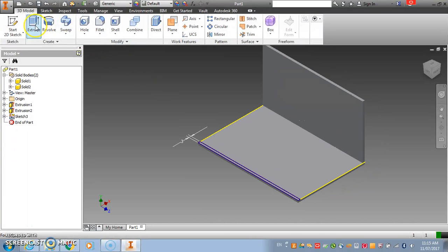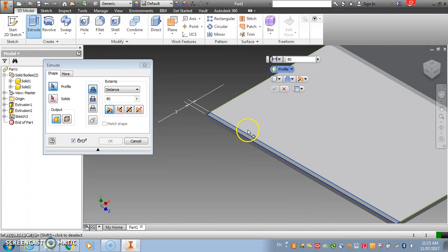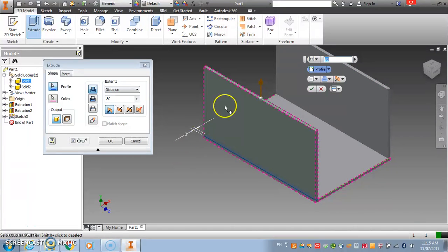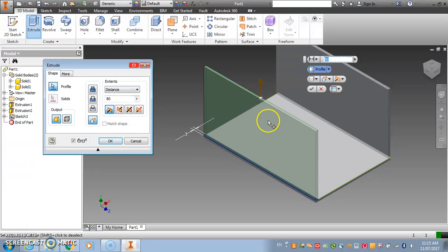So click cancel, go to extrude again, choose the correct area. Okay, the preview will show if it's correct. Then remembering the new solid, because this is a different piece from the rest. So click on new solid, and then when I click OK, you see another solid appearing here on the left column. Okay.